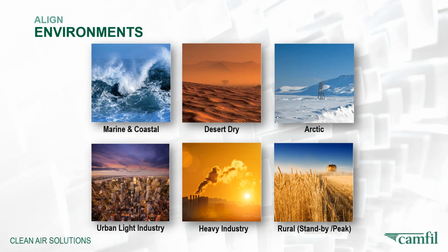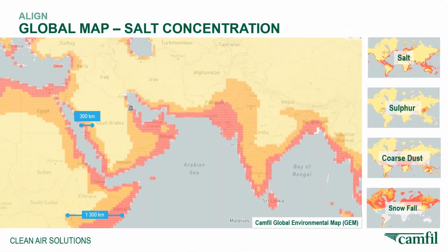In the Arctic, we'll use an anti-icing heating system or pulse system to remove the snow and ice. And then on the opposite end, in the warm and hot environments, an evap cooler or a chiller could be recommended, since cooler air has a higher density, which will lead to a higher output.